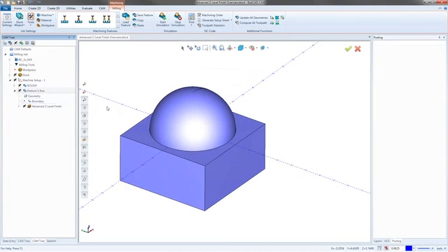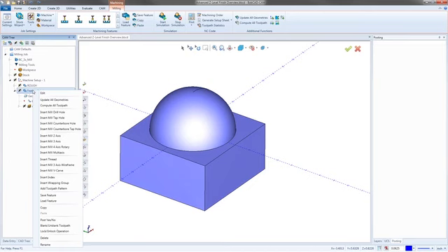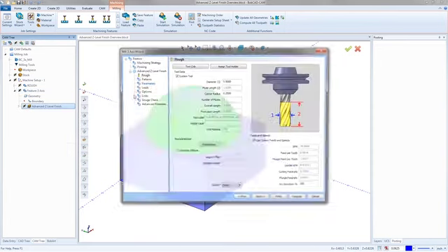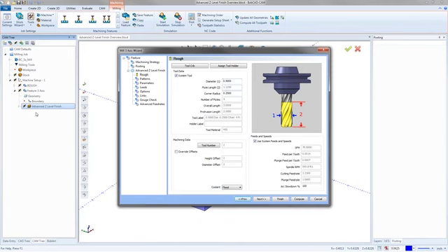And so inside the advanced Z-level finish, oh, and by the way, I just want to show you guys this in case you didn't realize it for version 31. You no longer have to right-click on the feature 3 axis to get back into the feature. You can now right-click on the operation you want to view and say edit, and it'll open you up to the tooling page for that feature. Really cool function. It's something that a lot of guys haven't noticed yet because I think most of us got used to never being able to do that. I still usually go to the feature, but just so you guys know, you can right-click on the feature or on the actual toolpath for the feature and then just say edit, and it'll bring you right back into that page. So cool.